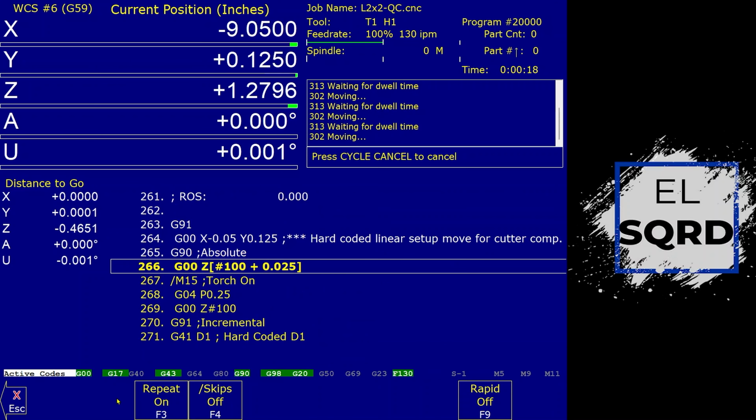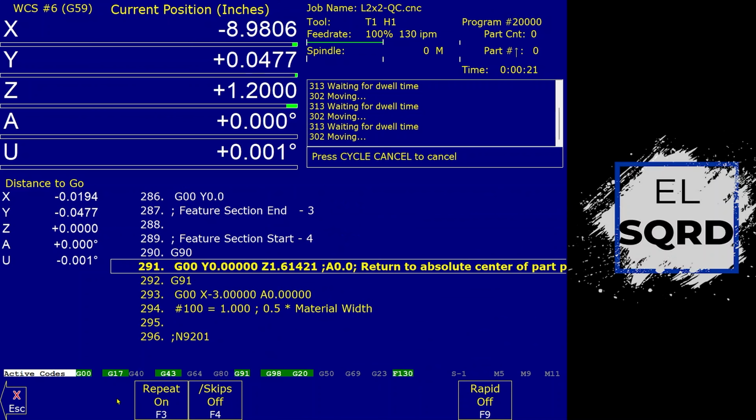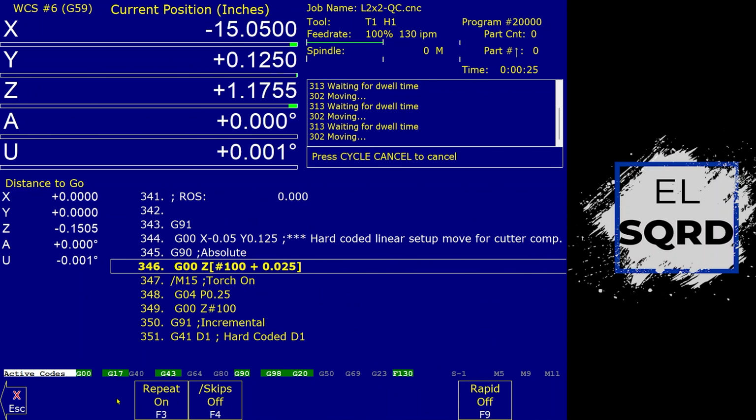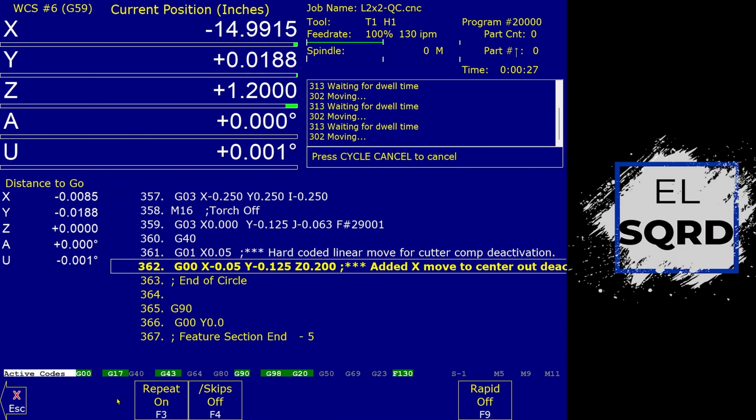It's not advisable to leave it in expanded metal mode for long periods, as it can cause excessive wear on consumables. Once the torch is cutting naturally again, allow the program to continue.